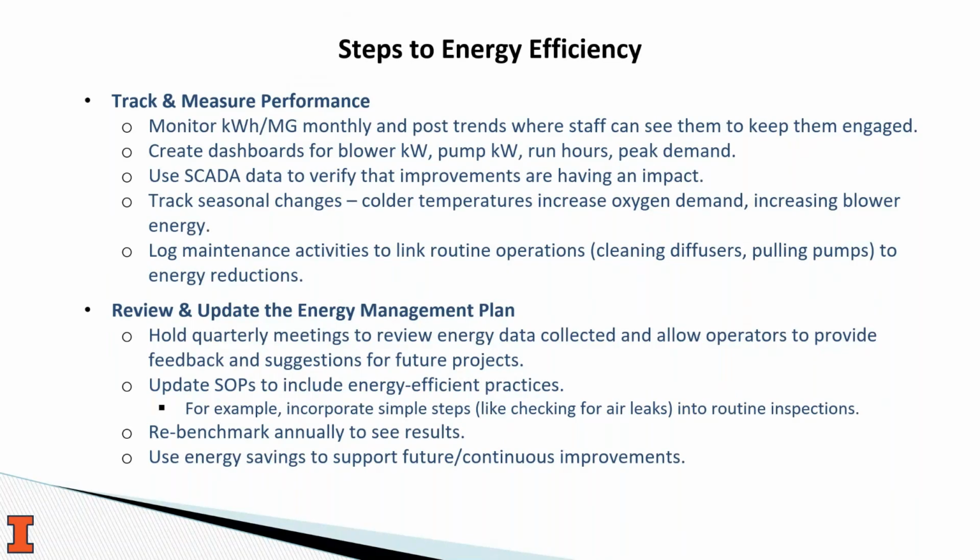SCADA data is also very beneficial for this. Reviewing SCADA data trends can help staff confirm that process improvements are having an impact, and helps identify things like seasonal changes, since colder temperatures often increase oxygen demand for blower energy. Linking maintenance activities to some of those external factors can help you see the real value of the energy efficiency project and the real impacts of how well they're doing.